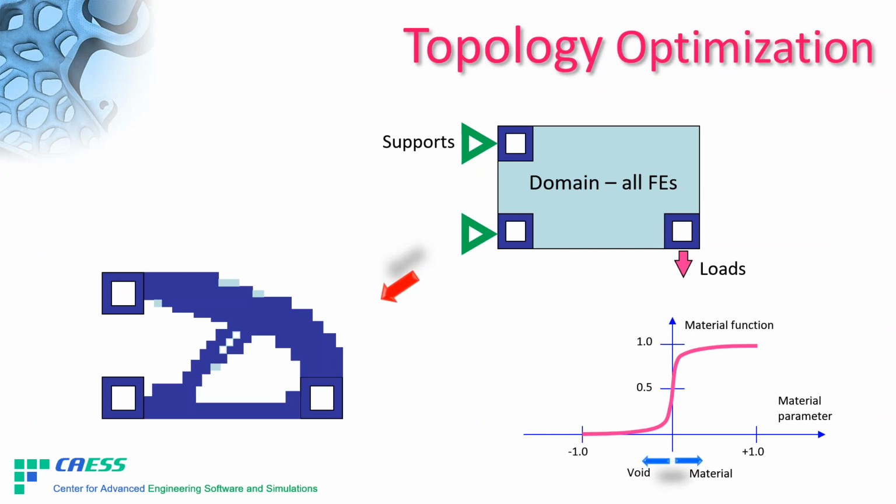Now, a few words about topology optimization. I don't know what the level of knowledge about this theme is, but okay, I will be short. From the numerical point of view, topology optimization is actually a process of finite element removal or later restoration by some numerical algorithm.